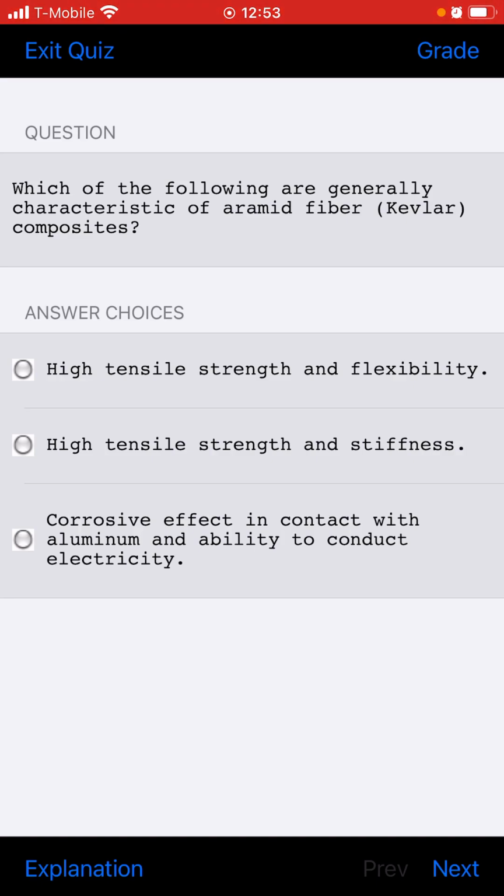A potted compound repair on honeycomb can usually be made on damage less than 1 inch in diameter.